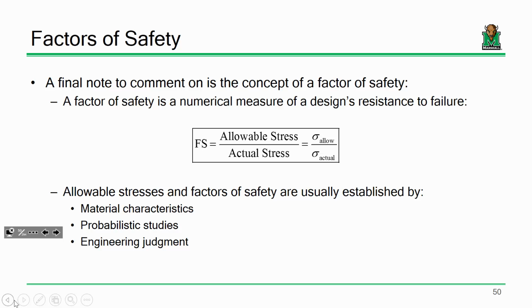In structural engineering, we do things a little different. We have a different design philosophy that you use because it's appropriate for structural engineering. For something like geotech, where the properties are so damn random that there's no way of capturing it, we just say factor of safety of 3, and we go with it. Because geotech is very complicated.